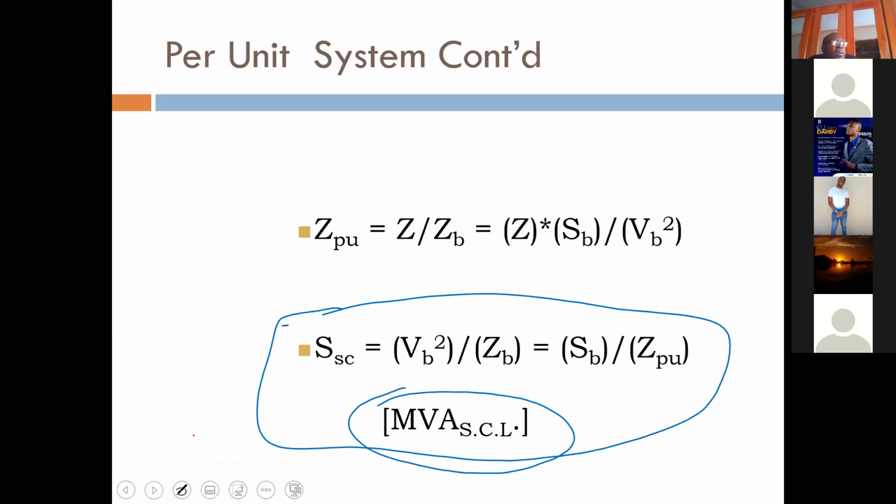In many instances, you may not necessarily need to calculate this. The program that you will be exposed to for power systems will do the calculations for you. So you'll get the short circuit level at the bus. And what this gives you is an indication as to the maximum current that the bus bar can handle without being destroyed.